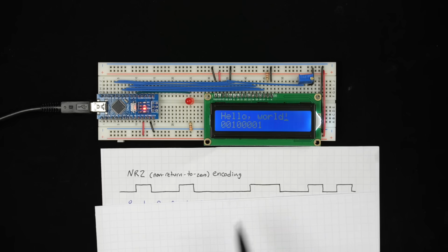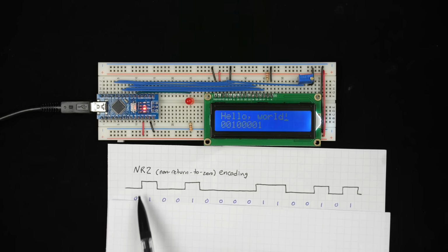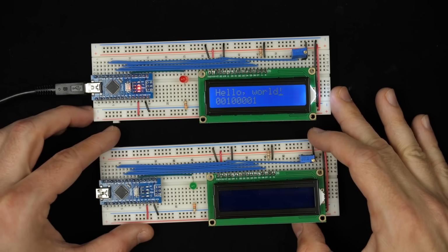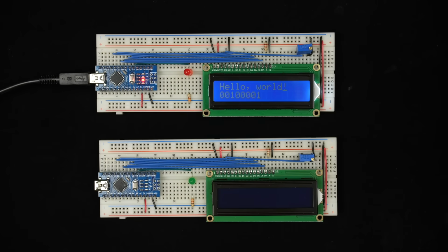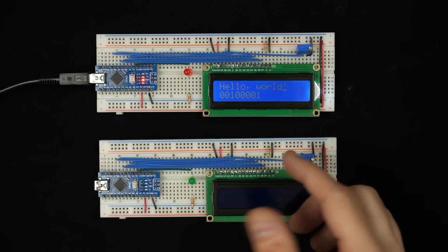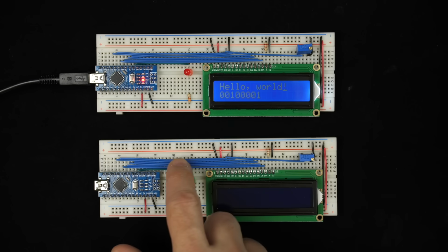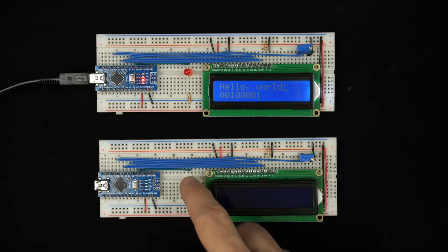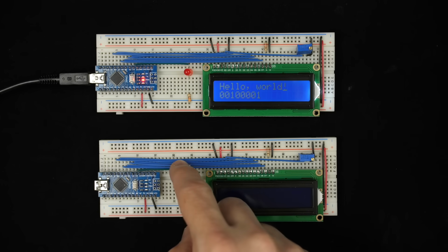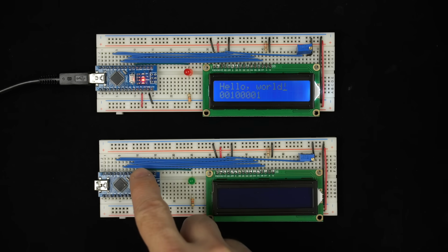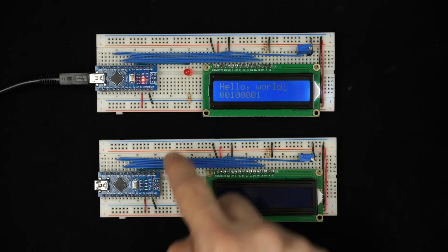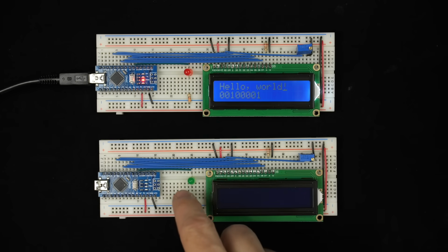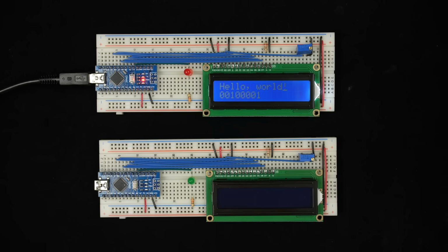So great, now that we've built something that will transmit this hello world message using NRZ encoding, let's move on to building a receiver. For the receiver, the hardware is going to be the same, because most of the hardware here is for the LCD, and the receiver is going to have an LCD as well. So it's going to be hooked up the exact same way. And instead of a transmit signal, we've got a receive signal, but I'm still going to hook it up in the same place. So I'm going to hook it up to D3, but now D3 will just be an input instead of an output. And we'll hook the output of this over to the input here, and that'll be the input for our receiver.